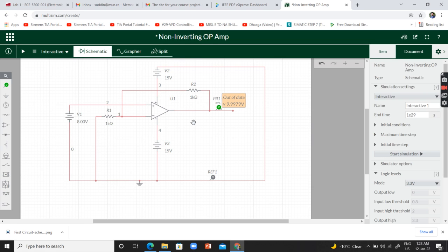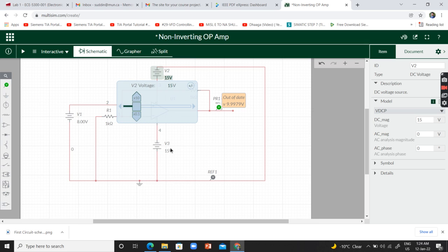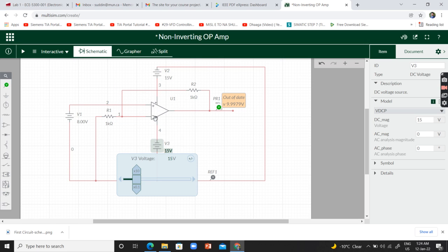So now again, a brainstormer, a question to all of you. What would you observe at the output? 8 times 2 is going to be 16, right? But the question is, what answer would you get at the output? You would not get 16 volts at the output, because over here you can see these values are the limiters or the saturation points, right? If the output goes beyond 15 volts, then the output is saturated to just 15 volts. You won't get 16 volts or 17 volts, right?